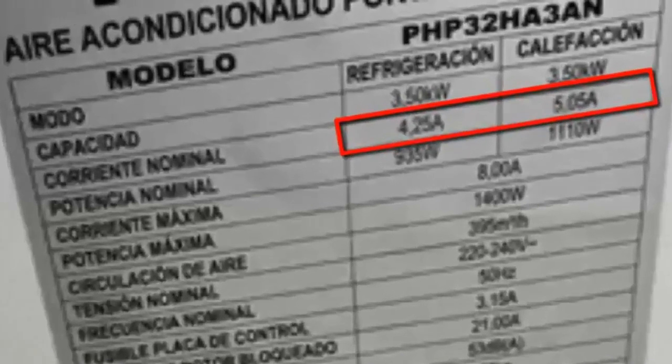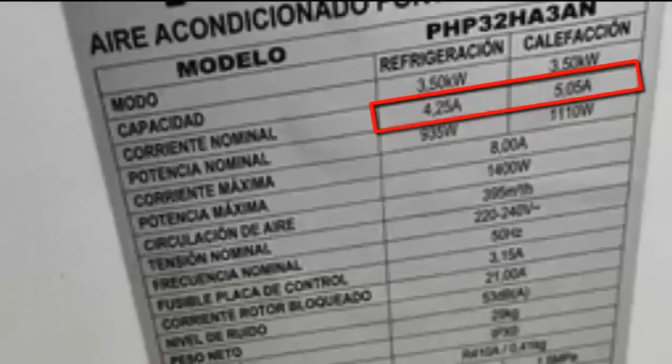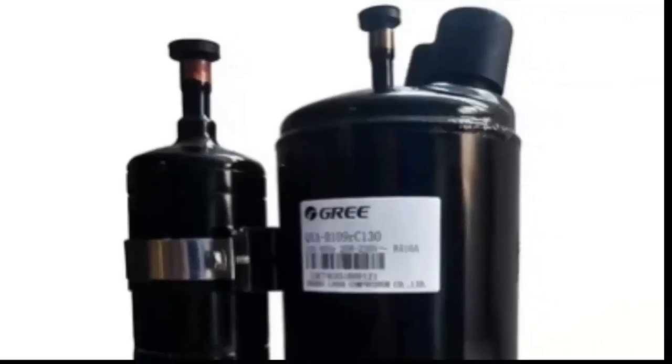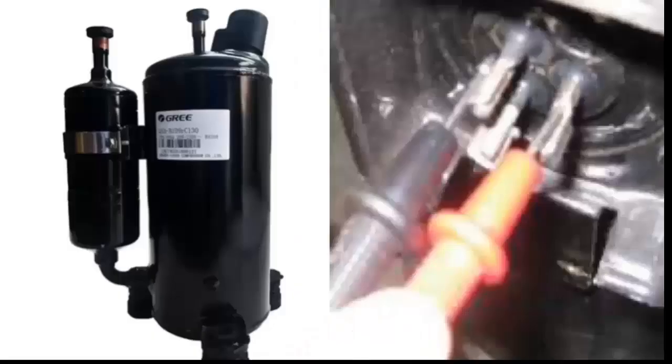4. Compare the value measured with the clamp meter to the unit's regular consumption, which can be found on the unit's label. This value is known as RLA. If the measured value is higher than normal, the system should display an error code before shutting down. In that case, focus on the compressor or the IPM intelligent power module located on the external electronic board.